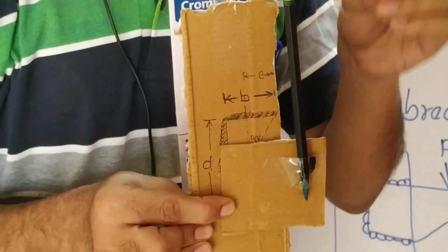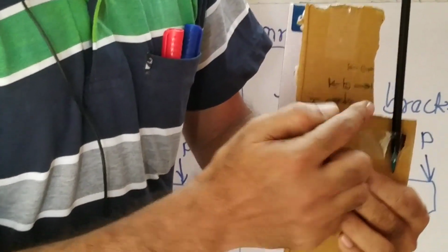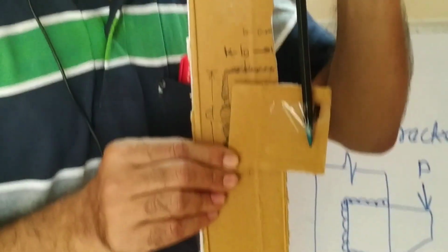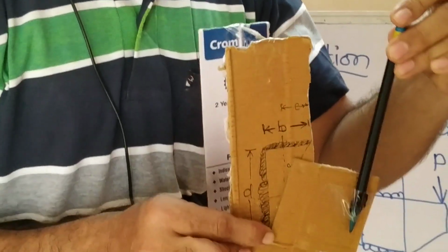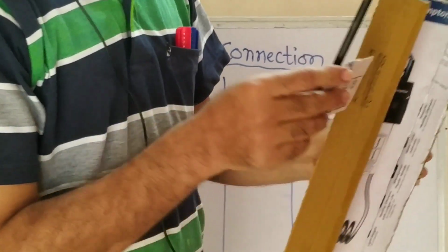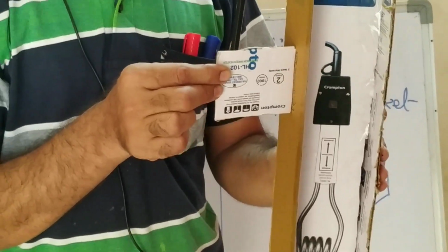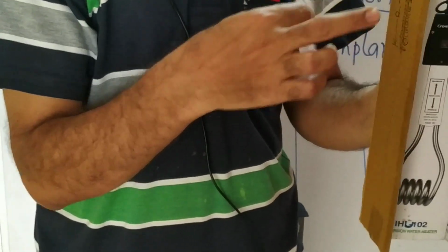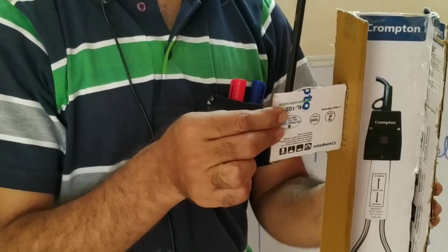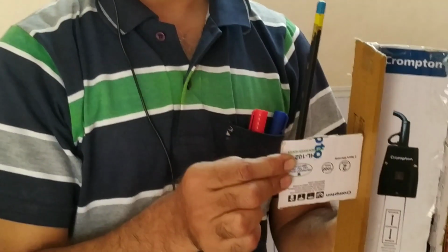So we need to work out the resultant stress at the extreme weld because of the shear, which is vertical, and due to the twisting phenomenon. Right? In case of out of plane, one is shear, second is bending. So the resultant stress at the top and bottom will be due to bending and shear. So this is what we have to find out.